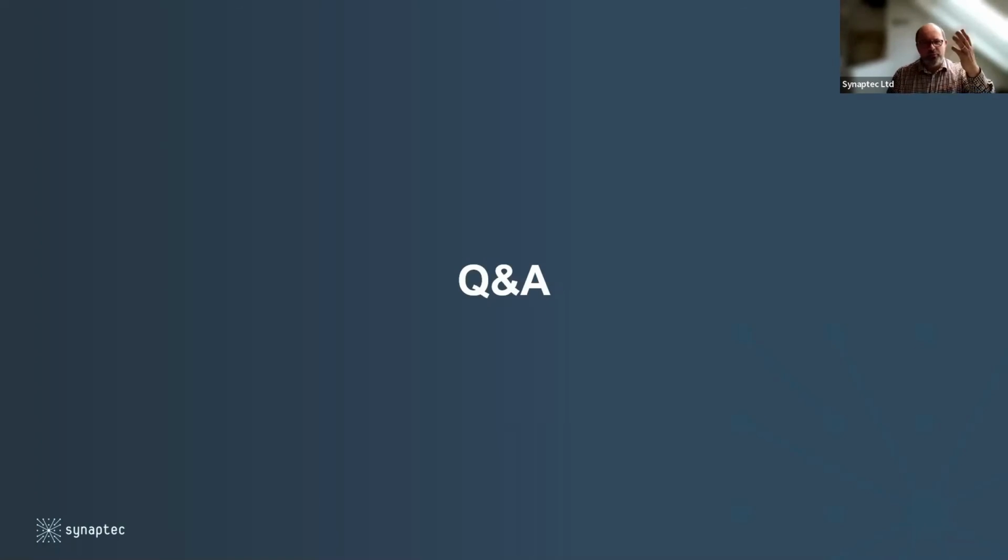But the screen grabs that you saw from Chris, at least, those are simple web browser interfaces where you can see this data online instantaneously from a standard computer or any web browser. And we natively publish this data in IEC 61850 sampled value format. That's 61850-9-2 SV. That's the standard in the power industry for digital communications and how you package and format and deliver this data.